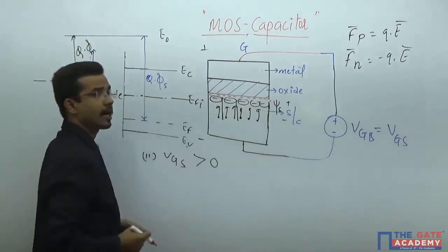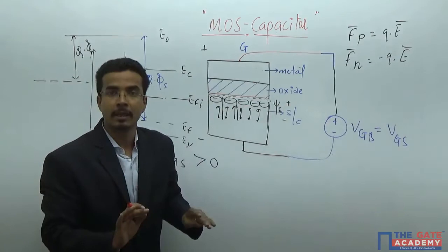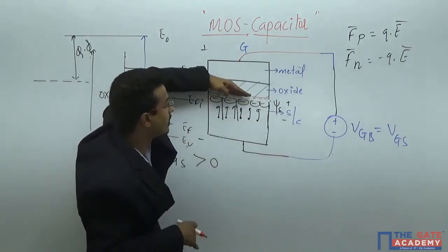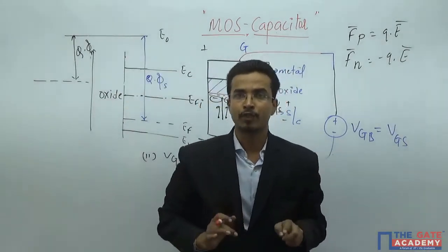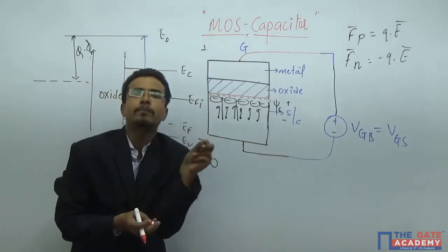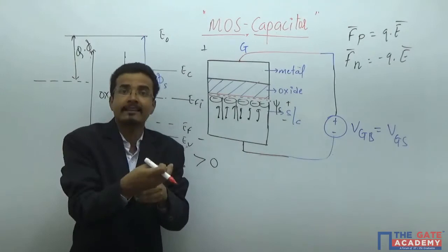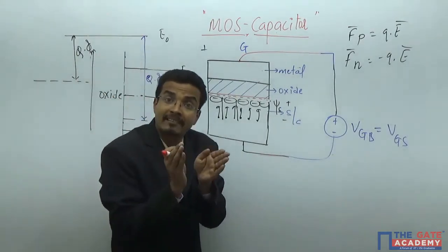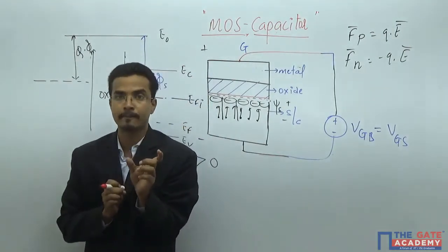These red ones are my free electrons, but you have trapped those charges between the insulator and the fixed ions. And whenever an ion is fixed, or any charge cannot move, that will carry some potential, or in other words, some capacitance also, if any charge is not moving from its position.